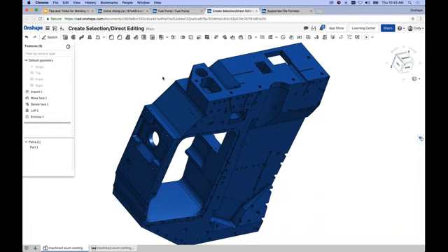But something to consider. I know a very common workflow that I get asked questions about quite often. Can you import models and then convert them from solid to surface and then do surface modeling work and then close it back into a solid? And the short answer is yes. Delete face with the leave open option is probably the most important tool in that workflow. And then from there, it's just constructing the surfaces or the geometry that you need to get it to the shape that you're looking for.